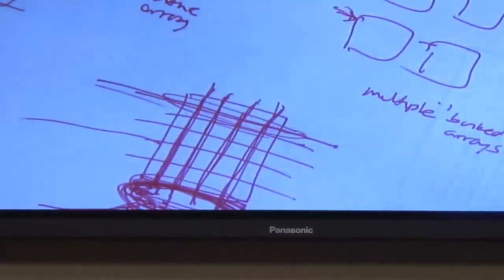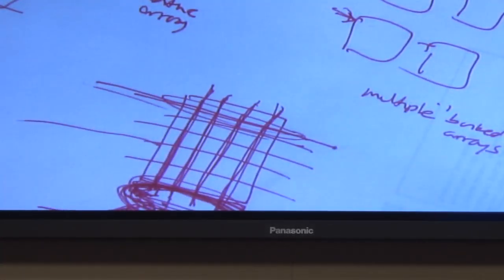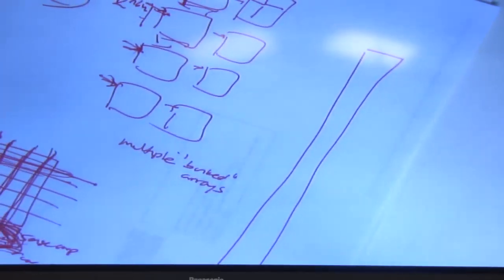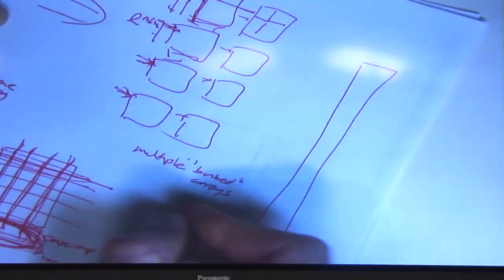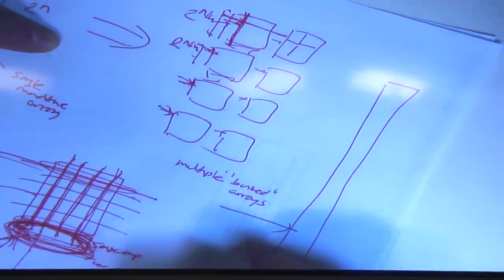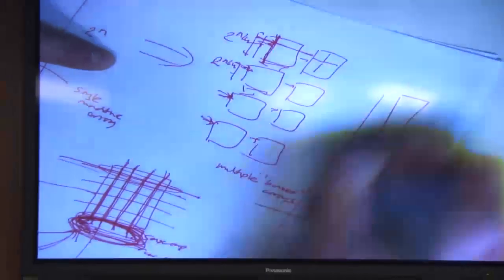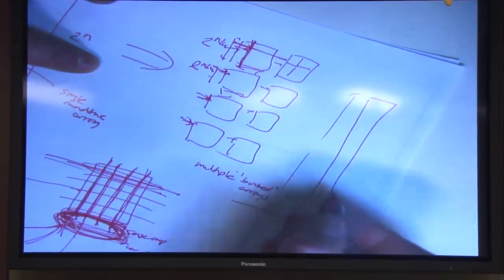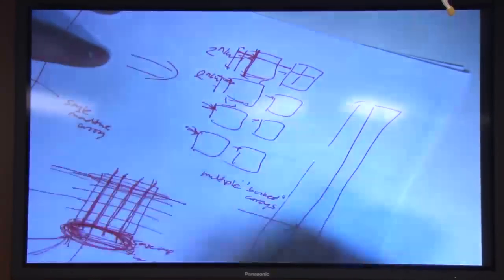But the reason it's done this way is because you need to actually have a memory array that operates that way, right? Alternative would be a memory array that looks much more slim, this way. And your interface is just 8 bits. And you have a bigger row decoder over here, right? This way you won't waste a lot of energy, hopefully, because you're not activating an entire row of 8 kilobytes.